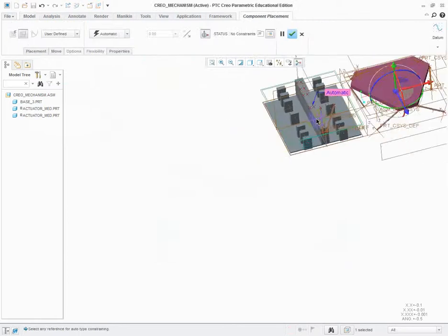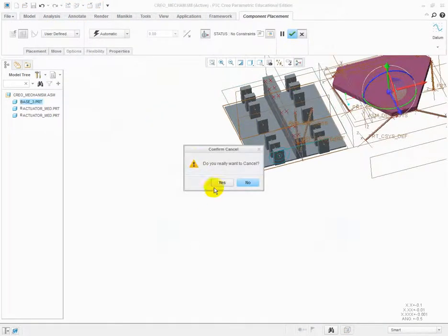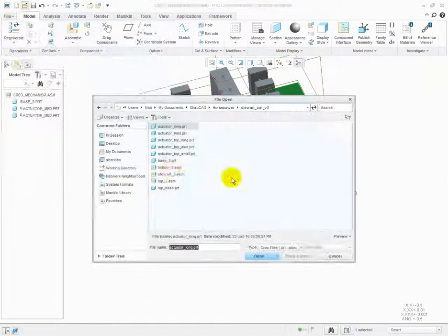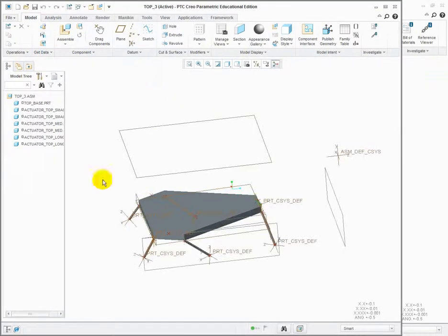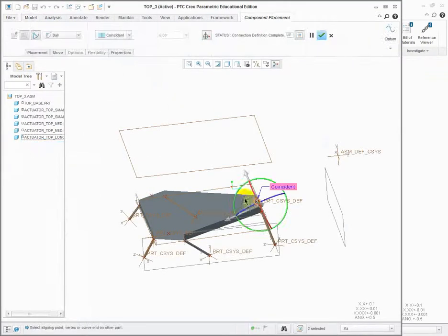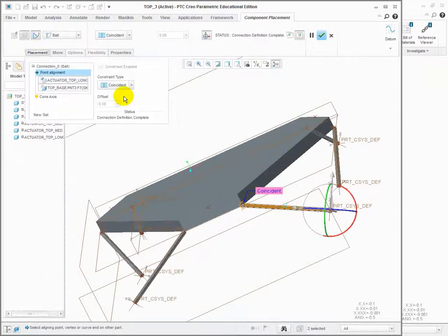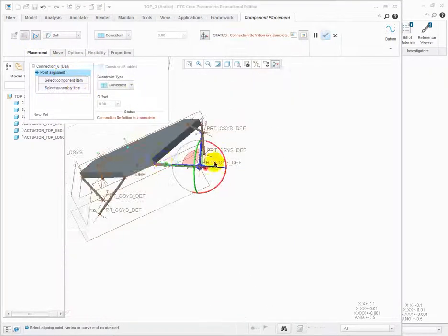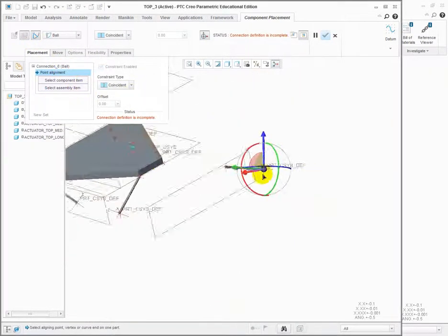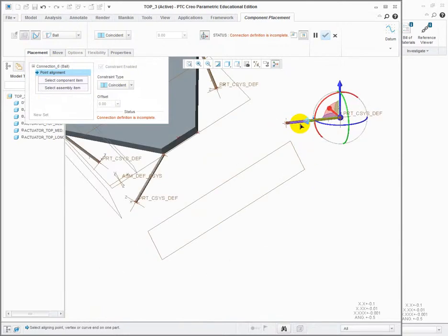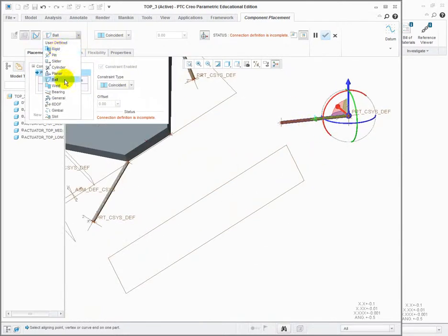Here when I made my top part, I used ball joints, so I want to open that up real quick so you can see it. So here for the last point over here, to assemble a ball joint, maybe I want to get my normal rod like I usually do, and here I just select ball.